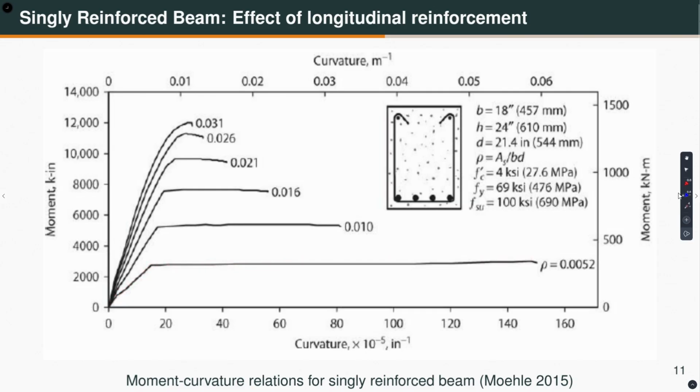What is the curvature ductility? Well, it is quite high. This is phi u and this is phi y, the yield curvature, when the tension steel is small. The behavior is tension controlled. If you increase the rho, let us say from here to here it is approximately double, the moment capacity kind of gets doubled, not exactly. So, the behavior is controlled by the tension steel.